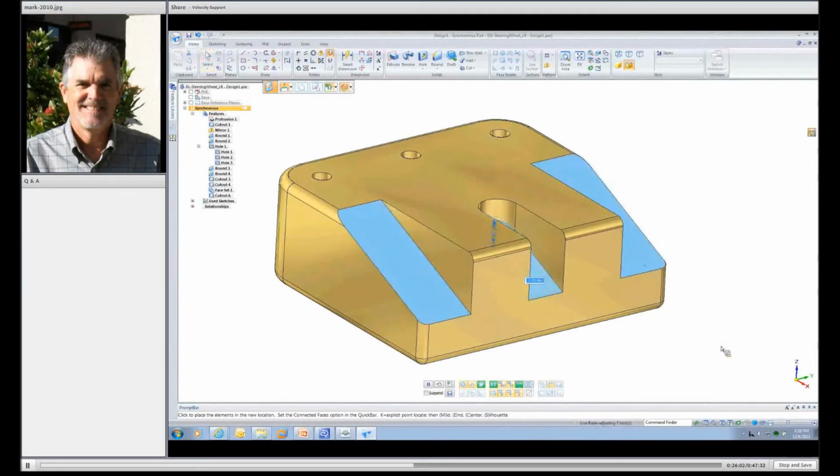you'll notice that that persistent relationship is still maintaining that coplanar condition. So you have the option to add face or different types of face relationships, coplanar, parallel, perpendicular, tangency, whatever you want, and they're going to always maintain those. Obviously, I have an opportunity to go over and make a change to it if I want to, or even delete that relationship.